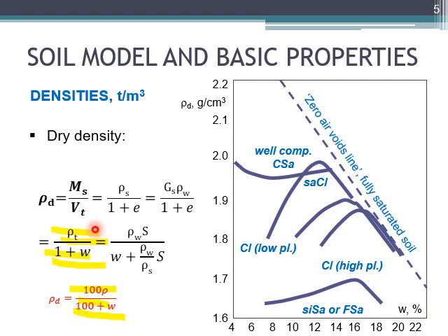From the Proctor compaction test, you already know that there are some soils for which it is possible to establish some maximum value of the dry density. But there are also some soils, called self-draining soils, where it is impossible. There is no one maximum dry density. However, for all soils, the dry density depends on the water content. It depends also on the soil type, and it depends on the energy of compaction.